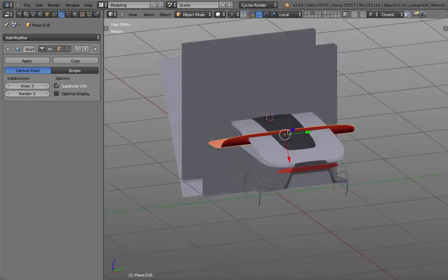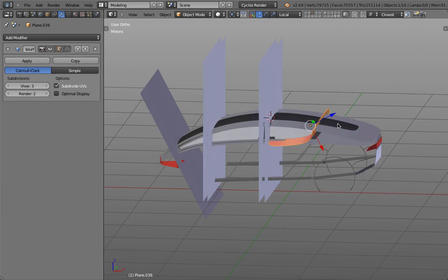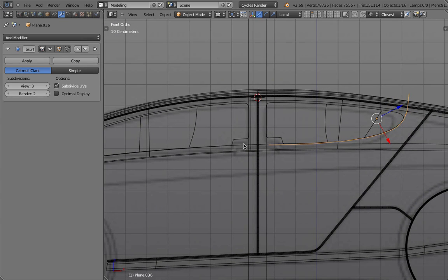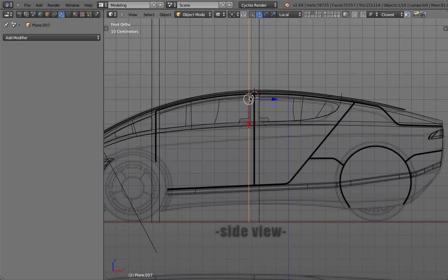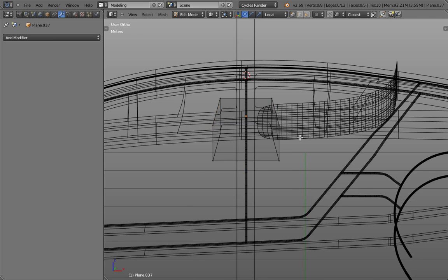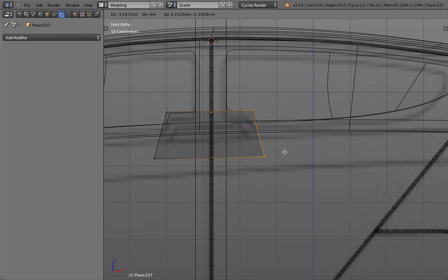I will utilize part of my car body actually to carve those windows out. And then also the other parts. And then here, for example, there is a small part for the handle. So I do this as well. Rotate, maybe scale along the x-axis. E, so I'm scaling this down. SX, try to hit the right angle, delete that face. And I notice this one is a little bit up. This one is a little bit down. See, this way I have the correct connection.